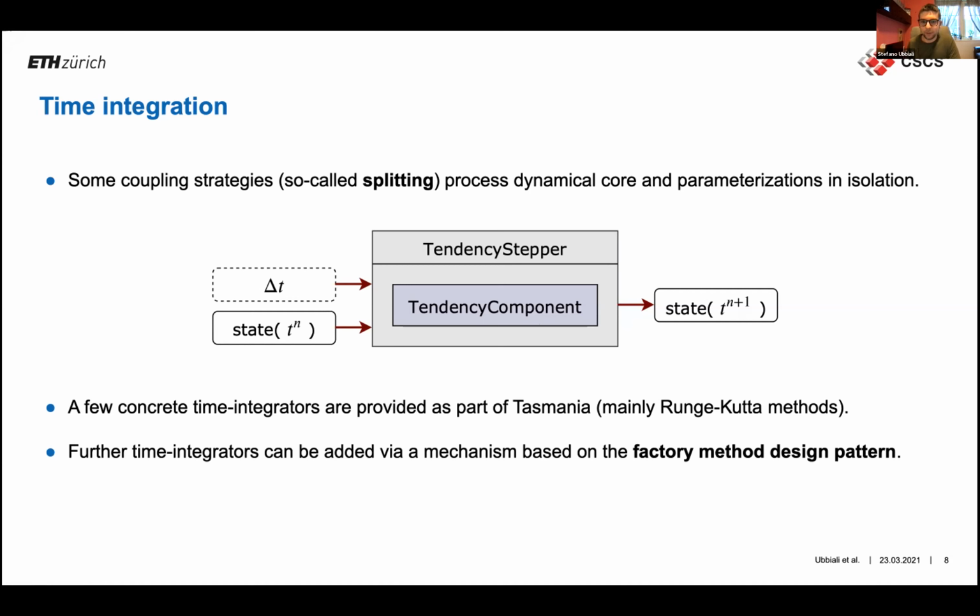So as part of Tasmania, we provide a few concrete time integrators, which mainly belong to the Runge-Kutta family. But of course, there are many other time integration schemes out there. In order to allow the user to add new time integrations to meet their needs, we provide an extension mechanism which is based on the factory method design pattern.